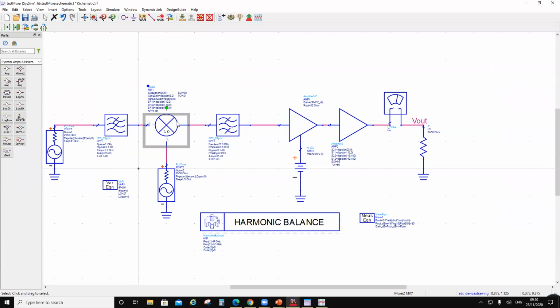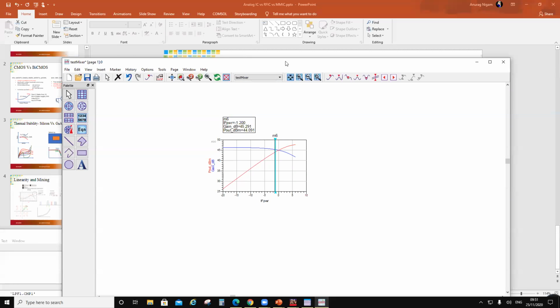Okay, one would be your balanced diode mixer, which is passive in the sense that it uses diodes, but it doesn't give a conversion gain. It is going to give you a conversion loss. And the topology for that, I'll show you what this design for a double balanced mixer is. But right now I'm going to show you what a Gilbert cell mixer is and what the constraints are in a circuit.